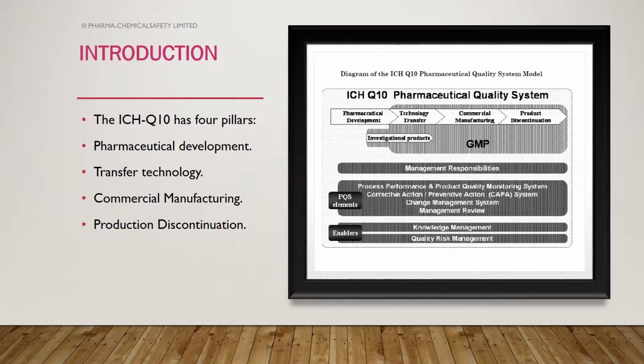So what can happen if you have a spill, etc.? Process safety gives you that. I forgot to mention that process safety is from two points of view. It's from the process safety that you can jeopardize the property and the society around, pretty much the public safety. And another is that you can jeopardize the environment as well. So either way, you need to have process safety. In the United States, you can find it in EPA 40 CFR 68, I think, and obviously 1910.119 from OSHA.